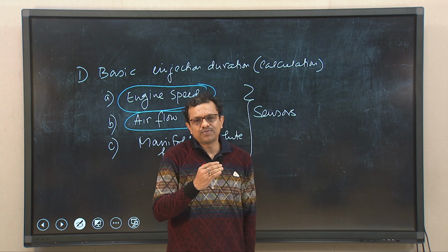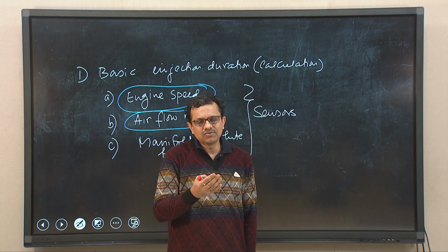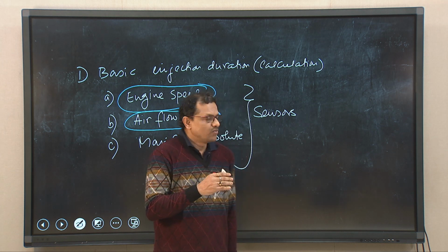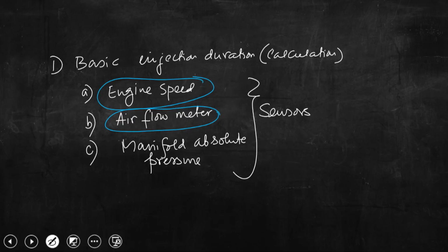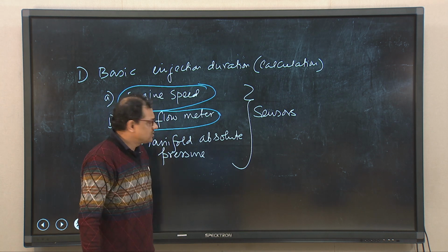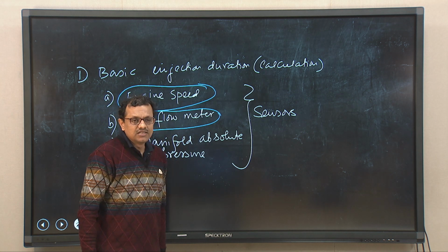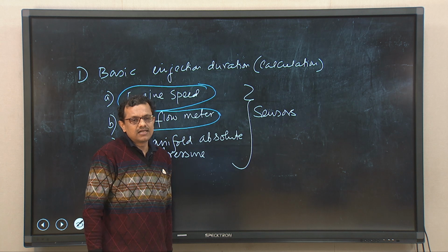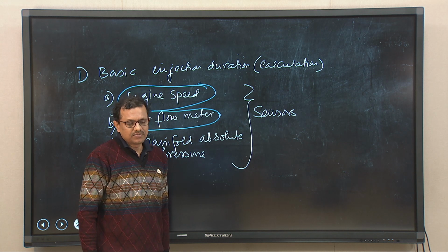Based on these two inputs received by the ECU from these two sensors, basic injection duration is calculated. To be precise, engine speed and airflow volume are regarded as the engine load factor.